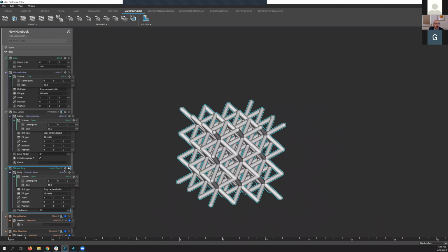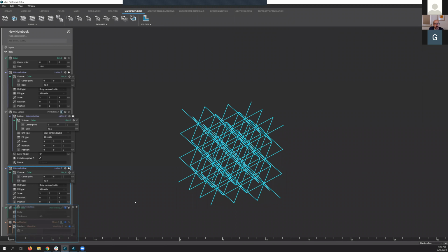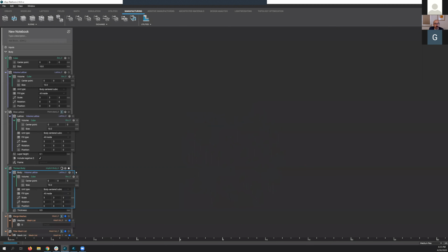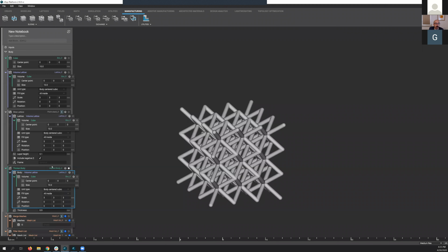Is this value propagating through correctly? All right. I think one of the last ones that I actually missed over because it just seems so intuitive now, and you may not have noticed it, is the hiding automatically of nested blocks. So we've added a new setting, and let's just pull it over. The setting allows you to essentially turn on or turn off this ability to auto hide nested blocks. So say I drag my lattice out, and I turn on the visibility. As soon as I drag that in, you see it should automatically turn off the interior blocks.